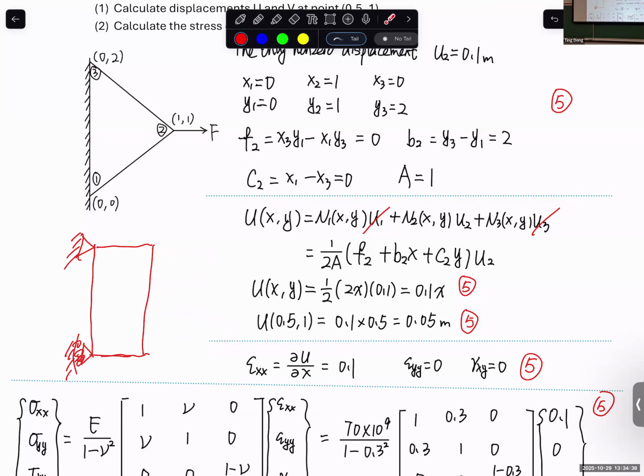In undergraduate mechanics of materials classes, when I apply tension here, I assume it is uniformly distributed. If you check the textbook, the first section tells you they made some variation, but in our undergrad class, I apply tension and it's sigma over A.